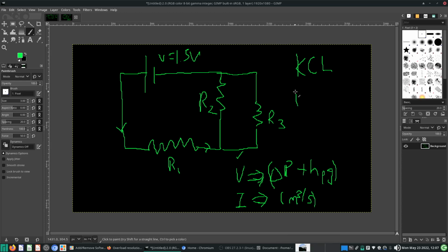Why? Because when you talk about power in a circuit, usually it's calculated like so. The power in a circuit equals the current times voltage, whereas when you talk about the power, the energy flow rate, it is actually the volumetric flow rate times delta P. Okay, you'll see that the units kind of work out. Because PV equals a work unit.